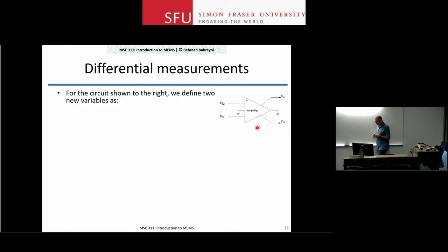So how do we deal with differential amplifiers, or analyze differential amplifier situations? It's going to be easier if we make a definition here. Let's assume that we have this amplifier circuit. VI1 and VI2 are the two signals that go into it. We always know that there are some power supplies, and Vout is at the output there. Actually, Vout should not be grounded, it does not need to be grounded. So I'm going to fix that and post the proper slides on the website.